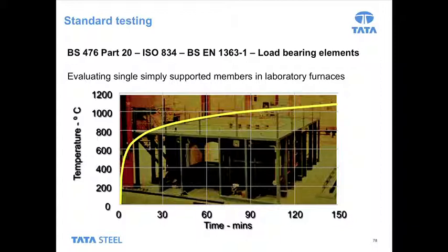Now in practice, this is an extremely severe fire test, and very few fires in real buildings will get to the sort of temperatures or last for the sort of durations shown by that time temperature curve. We also should note as well that the time temperature curve continues to increase in temperature as time goes on. And in practice, it's very, very difficult to achieve that.